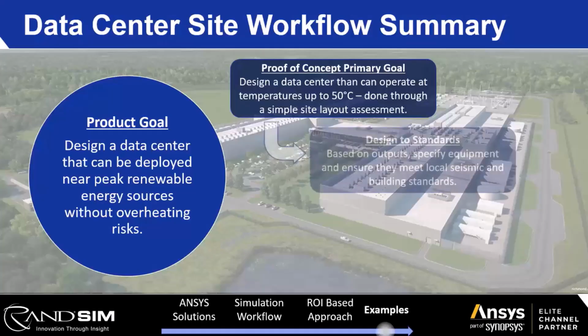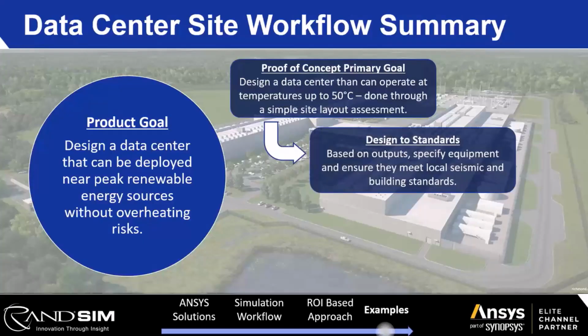understand and spec out equipment so that by the time you move into designing the standards, it's no longer a fight with the chiller manufacturer because you need them to get an extra 5 degrees Celsius to cover it. It's, hey, I already knew off the bat that these 3 manufacturers are out of the running because they can't produce a chiller with adequate standards for what I need. And I need to move with these 3 chiller companies.